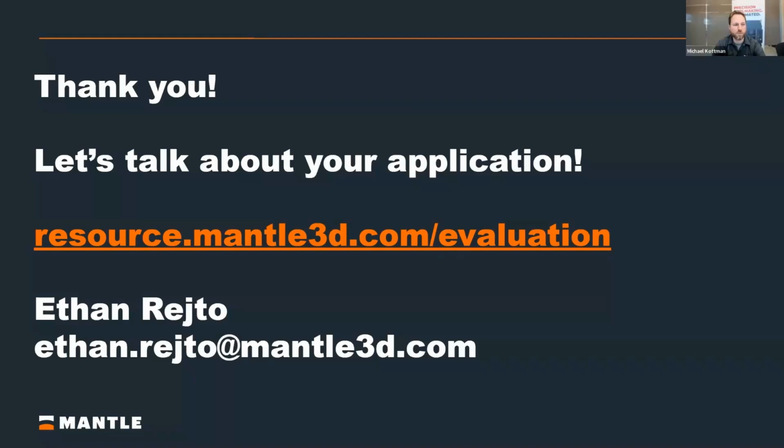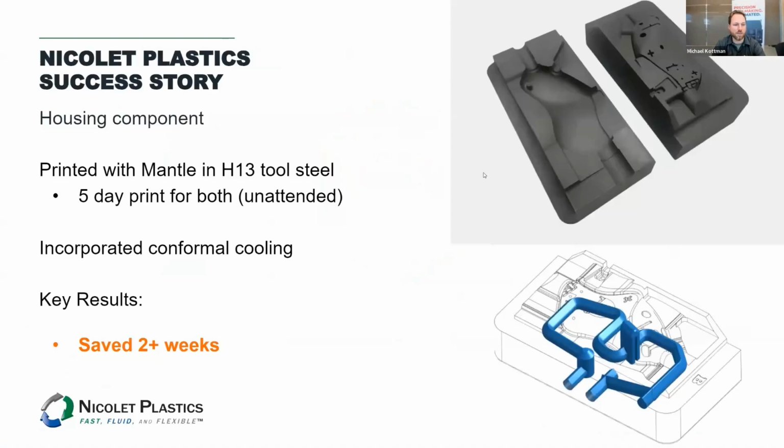Yeah, mostly customers are dropping in their existing tool design process. We have customers who use really sophisticated software to model the impact of cooling channels, and they can use that today to design their tooling to perform optimally and account for shrinkage in the mold. The one thing that comes up often is the design of cooling channels. Because we're printing in this three axis system, we'll typically teardrop the top of the cooling channels, which is a lot easier to close. We can print circular cooling channels of a certain size, but we typically recommend the teardrop process.